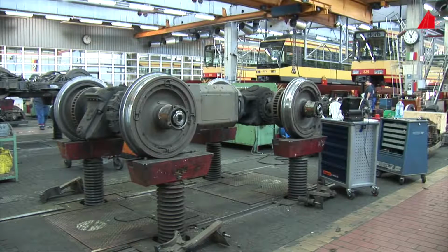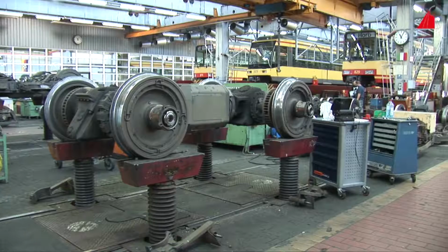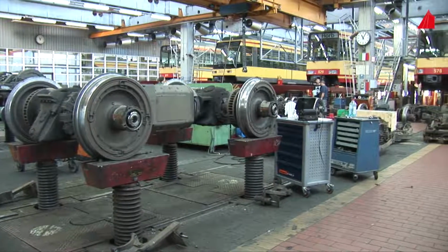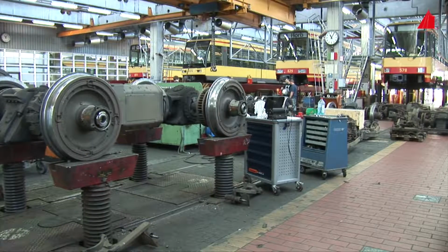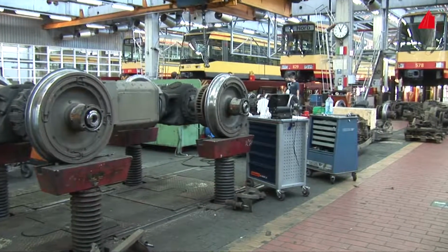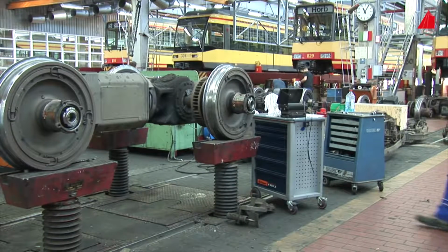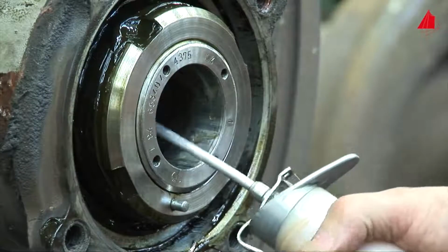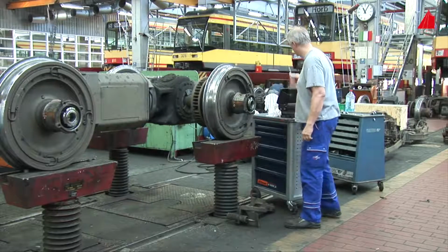This is one of the bogies jacked up to comfortable working height and prepared for ultrasonic inspection. Special attention is given to the wheel axle, among experts known as wheel set axle. It has been designed as a hollow axle. This saves weight and facilitates the ultrasonic examination. The material tester applies a suitable oil as a couplant into the bore of the axle.